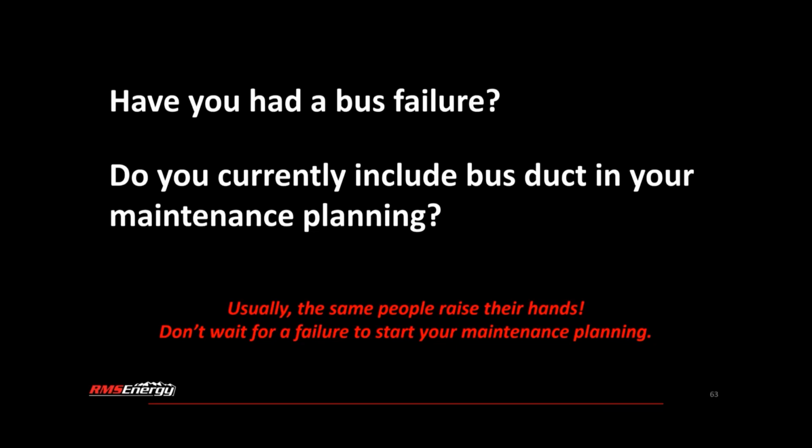Okay, is it okay to remove the fire barriers and continue working? Or continue operating? Yeah, I mean, you can. The reason the fire stop barriers are there is to prevent that smoke and debris from entering the rest of the bus duct if you do have a failure at your transformer. So there's nothing that's going to cause your bus to fail by removing that fire stop barrier, unless it's also acting as a seal off bushing. But you have to evaluate that with what type of design you have in your system. But in general, it's an added protection to eliminate debris and contaminants from entering the rest of your bus.